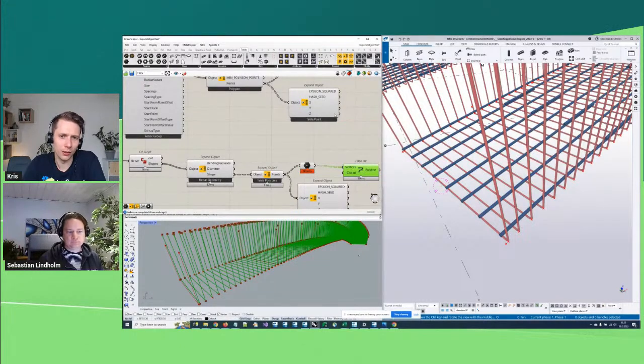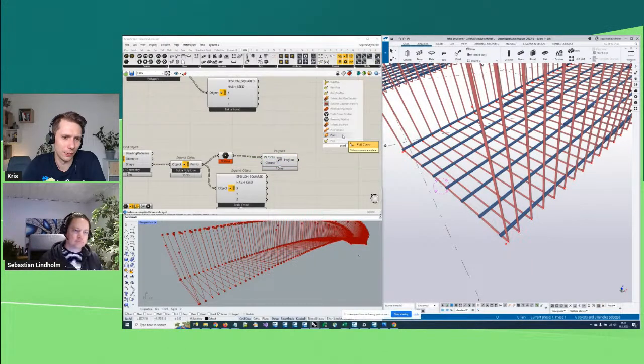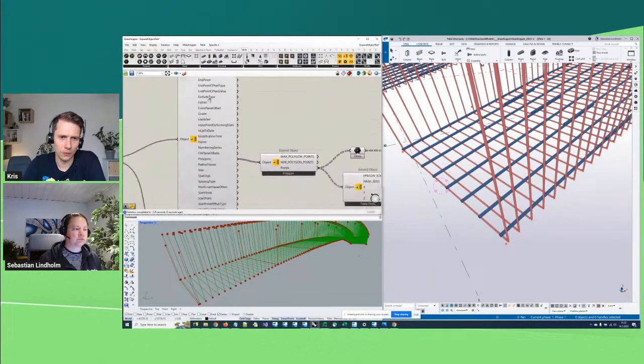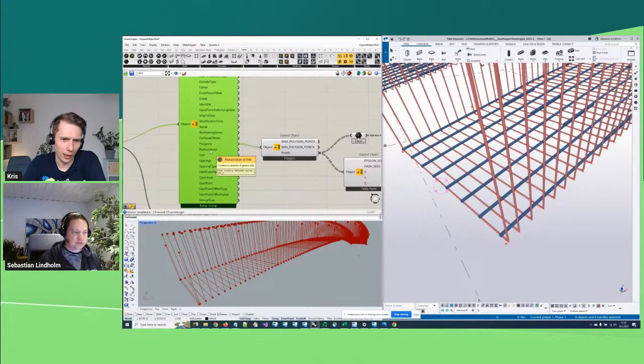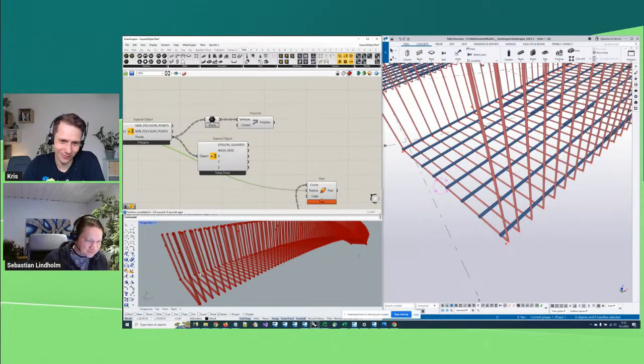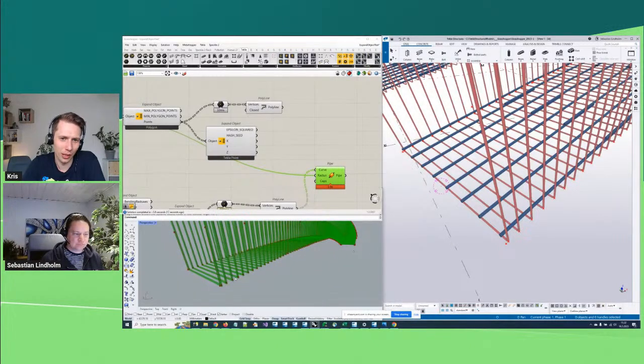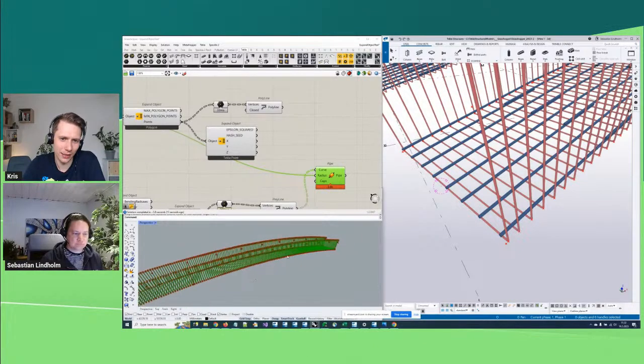And of course you can also connect this polyline to, let's say, a pipe component, so you can also get the radius, a 3D shape, for those who are interested. So maybe you can also get the actual size in Rhino. Yeah, that's a fair point, because we do have radius values. That's just a number, so I can use that directly. Make sure if you do not have meters, it should be millimeters in this case. So there you have some thickness on them as well. Yeah, so this is also a good way to visualize how reinforcement will look in Rhino.